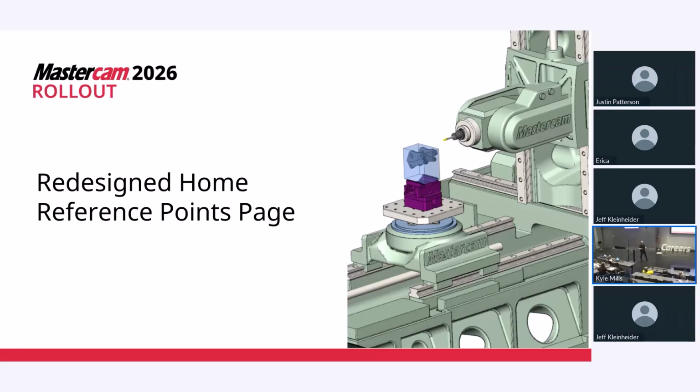So how annoying is it when you're doing 3+2 and you're doing one side, you get the spot you want to retract out all done, and then you go to the other side, it's like, okay, I copy that over, now it's going to crash through my part to get back over there. Now you can actually use the tool plane as that. So if the tool plane's centered and you just flip around your tool plane and C plane, it's gonna do the right thing. So let me show you what it looks like in 25, and then we'll do one in 26 as well.